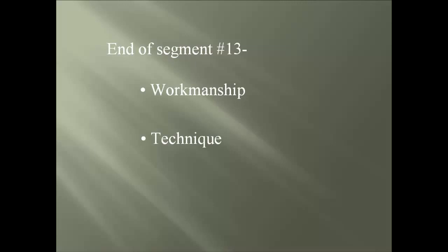Then we covered the technique of welding reinforcing steel, which revealed the strength relationship of the filler and base metals, and also the how-to for determining the correct combinations provided by Table 5.1, while being alerted on the why the carbon equivalent number is so important for establishing the preheat and interpass temperatures.